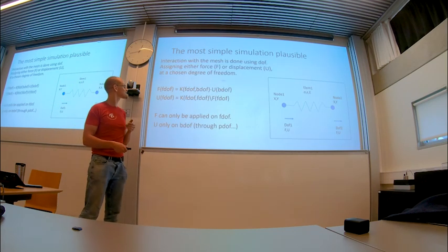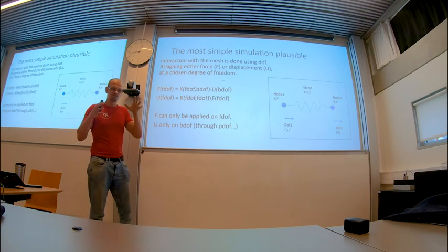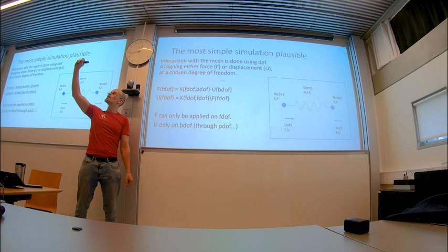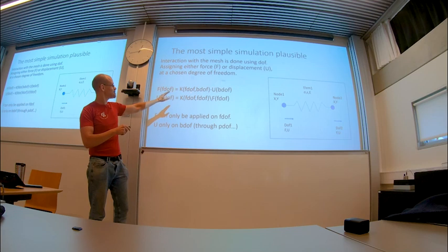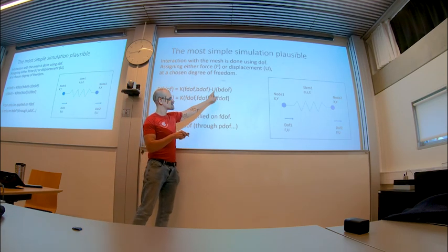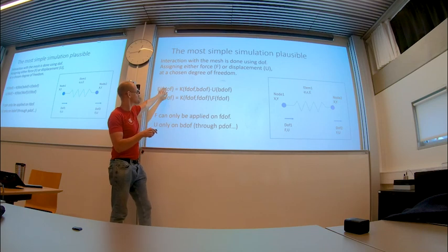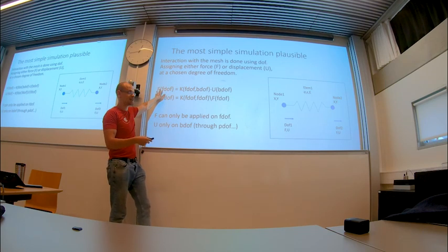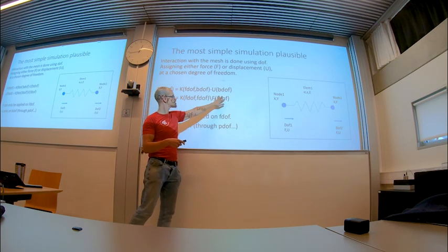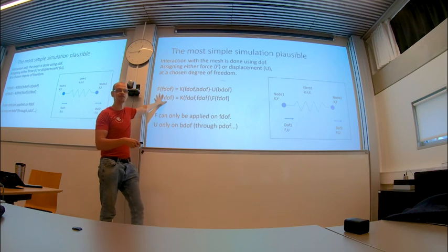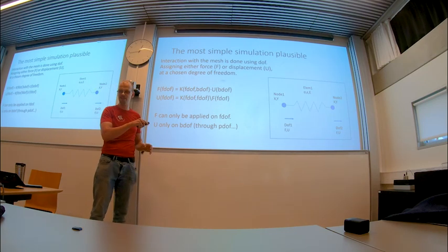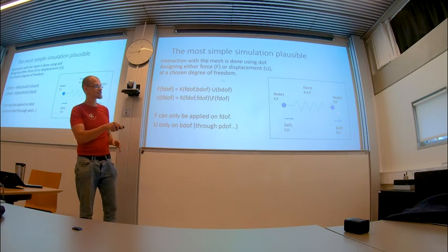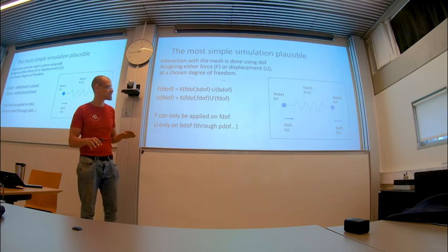And elasticity is amazing in the sense that if you have millions of elements connected together and you move one of them, you do this equation here, and like magic, you move 1 degree of freedom, it gives you some initial force distribution within the element, and then these forces are put on the elastic, and you get the solution of final displacements of the whole million nodes. So this is a magic equation. There's a lot of math in it, but you can apply it in this kind of redundant, simple way. You can make anything with it.